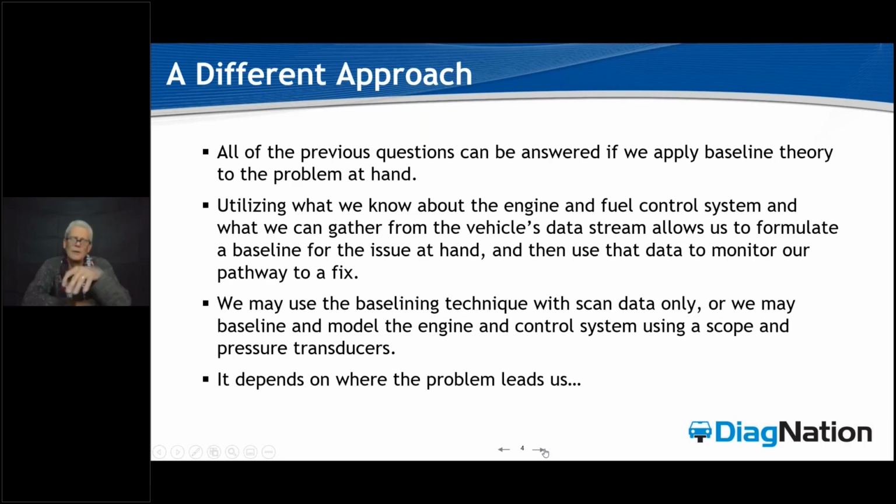What I mean by that is let me just cover it now so I don't forget. If you consider the altitude factor here, it is the number one and only reason why a manufacturer does not and cannot give you a very specified number for any given sensor while the engine is running. And the reason for that is it's the same system at sea level as it is at 7,000 or 9,000 feet in Colorado or 5,000 feet. Okay, and so what happens is the manufacturers have to give us a diagnostic range when we're looking at these codes.